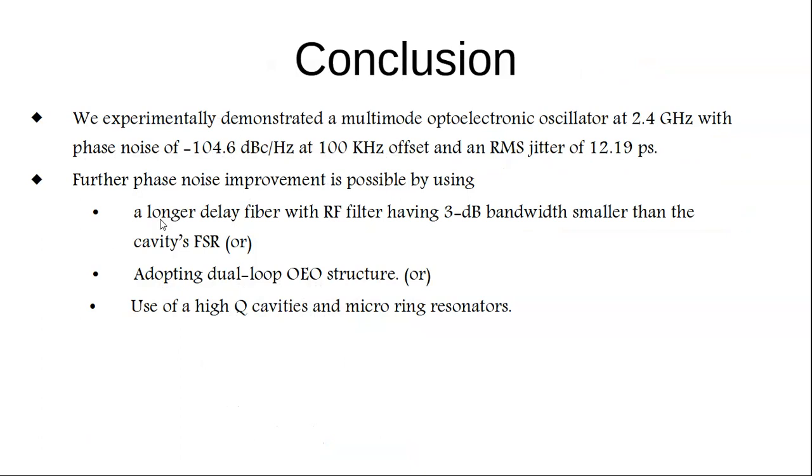In conclusion, we have experimentally demonstrated a multimode optoelectronic oscillator at 2.4 GHz with a phase noise of -104.6 dBc per Hz at 100 kHz offset and an RMS jitter of 12.19 picoseconds.